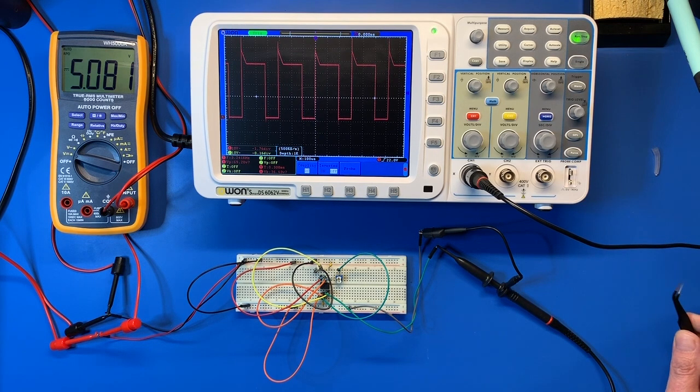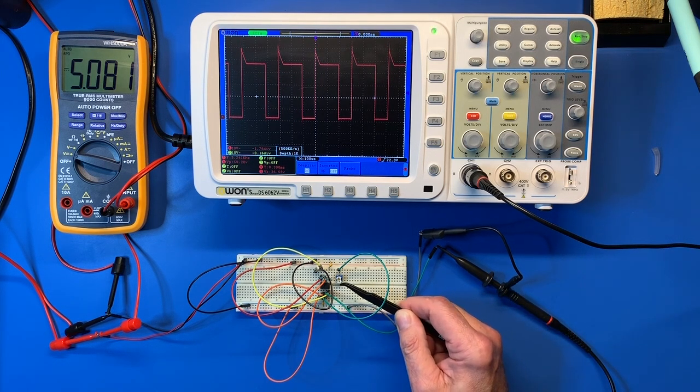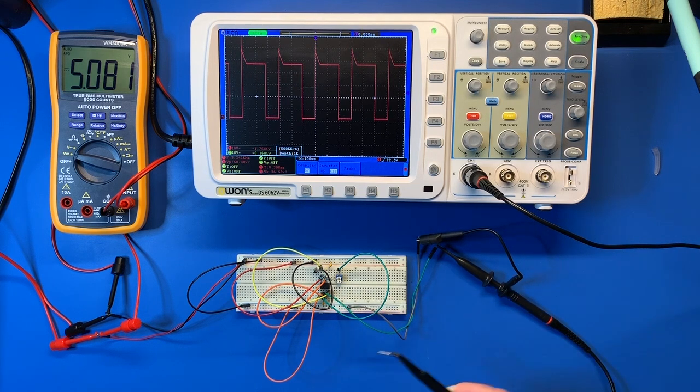So we were looking into the switching problem and why we have that situation occurring. We do know that because we have these long leads, it adds parasitic resistance and capacitance, which complicates the nature of this 555, which has transistors inside that are switching on and off, on and off. Anytime you're switching, you have sudden draw of current, and any micro resistance that occurs causes voltage to shift and can induce various characteristics in the waveform. In looking at this,